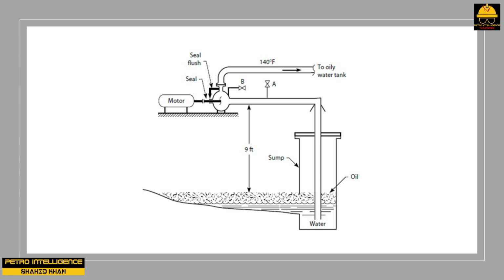However, he then noticed an interesting phenomenon. The pump would continue to run for about an hour after it stopped raining. It produced a discharge pressure of about 100 psig. Then, quite suddenly, the discharge pressure would drop to 70 psig and the amp load on the motor driver would drop from 20 to 14 amps for its last few minutes of operation.